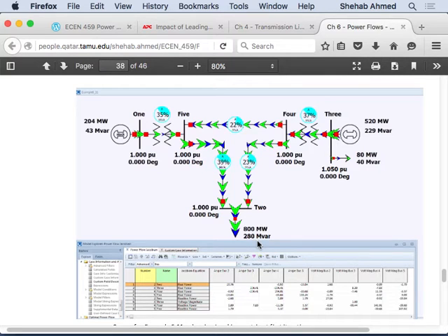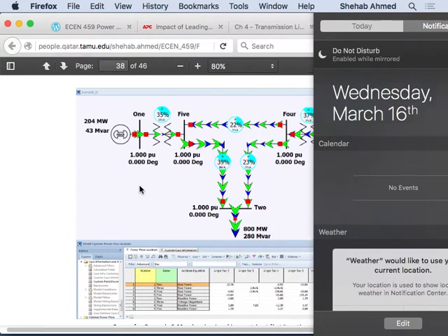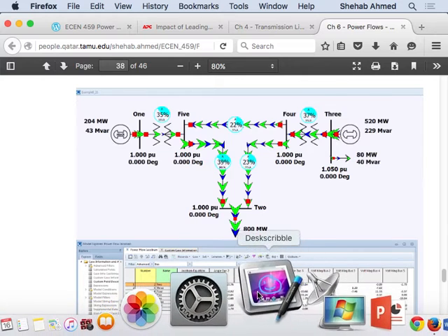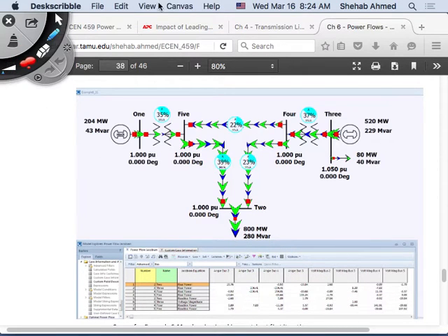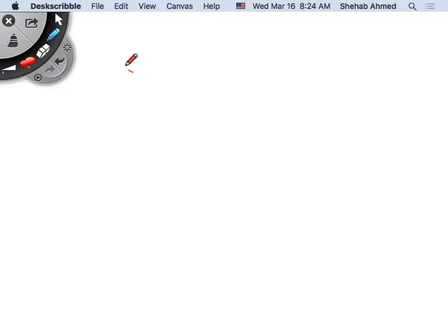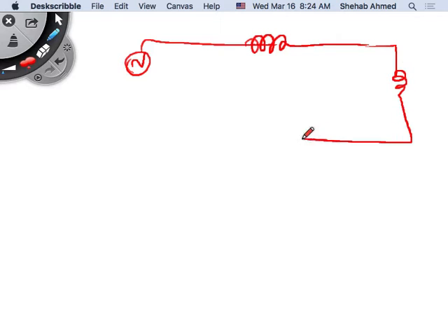Does it make sense in this case? I don't care what the rating of my induction motor is, but what I did was play with the voltage in this case. When I put a pure capacitor to supply the local reactive power, I don't have the drop across the line. What is this? This is my line's reactance.